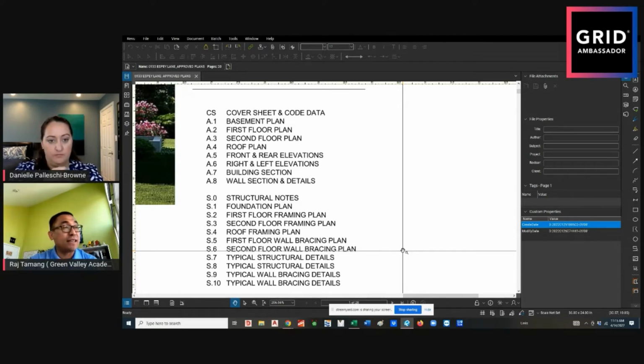There are some places like DC where you definitely need electrical, plumbing, all that. In Maryland, I believe they need it too, but in Virginia we don't need it. So you are asking how are you going to do HVAC? Our HVAC contractor will submit a separate permit with a calculation. It's called Manual J calculations with ductwork layout, all that they're going to submit separately. Got it. Okay. Yeah, but you have to remember, even though they submit it, as a contractor you need to coordinate with them, make sure where they are putting the ductwork. I don't want the ductwork everywhere on the basement ceiling, bulkhead, right? So you have to place them in a way that it doesn't look ugly. So that's something you still have to coordinate with them, but you don't have to include it here as part of the permit documents.